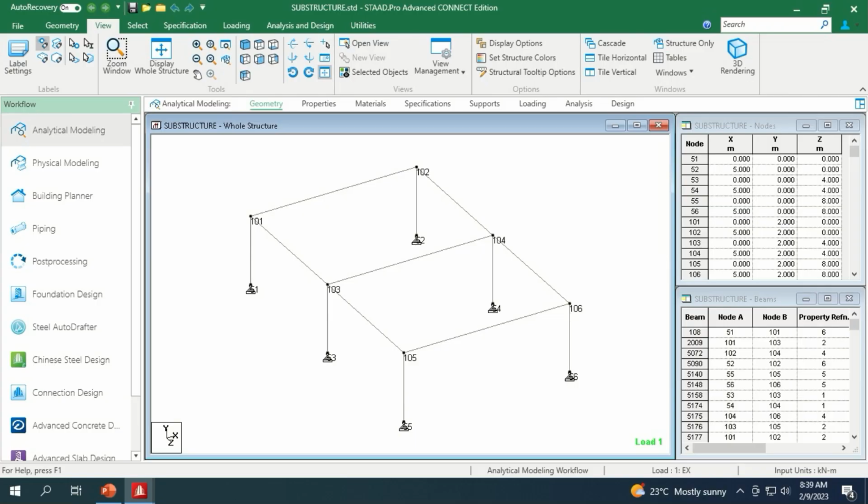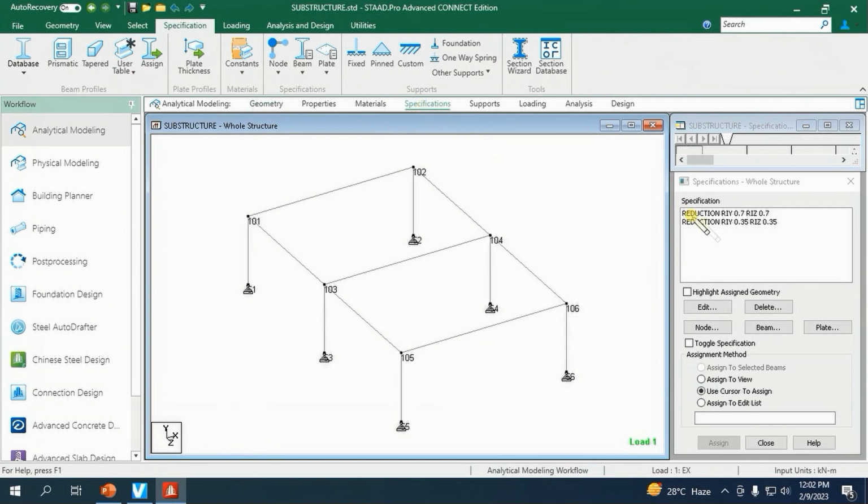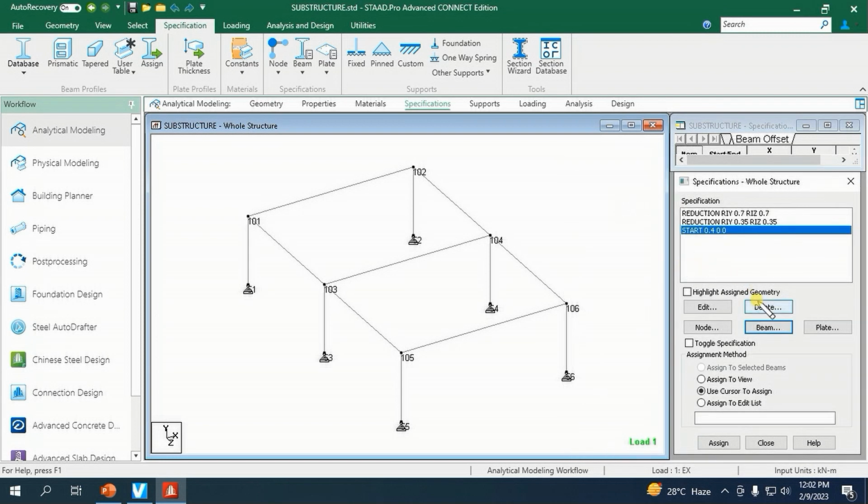We can assume a positive moment of 300 kN-m for every column where the footing is eccentric. We can assume 350, 300, and 200. Or another way is to offset these columns by, let's say, 0.4 meters and then get the moment in the output. So we can have a preliminary moment to use as an assumption.